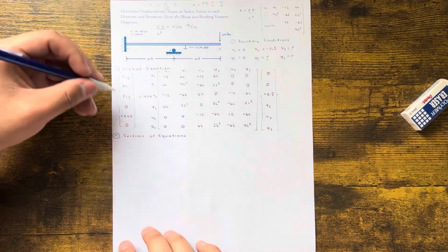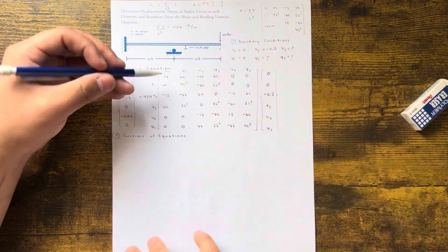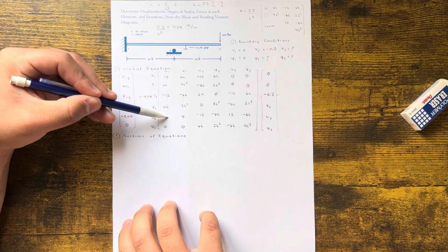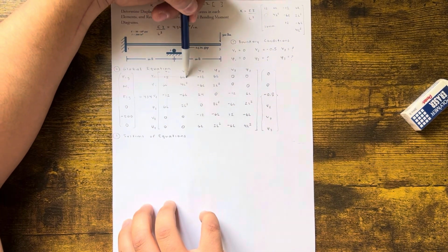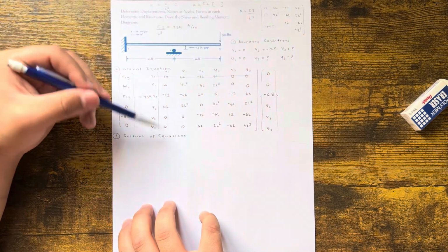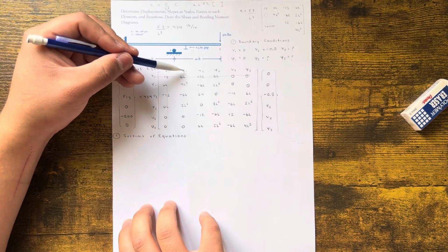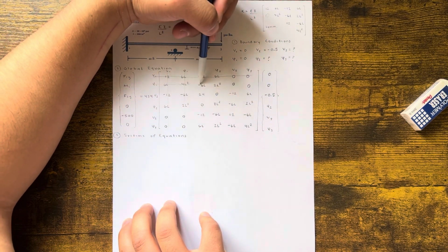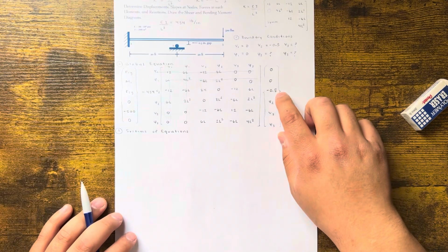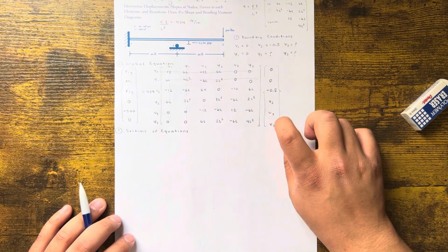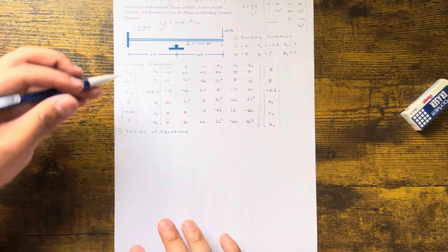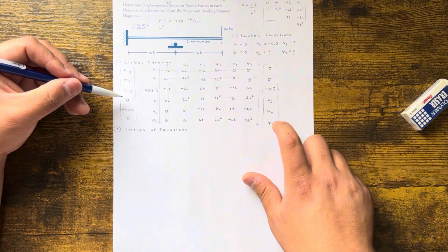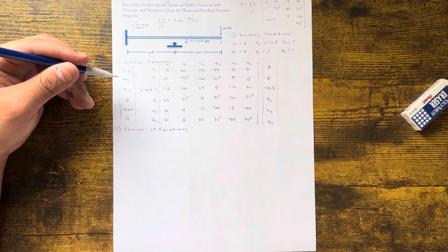So equations, right? When you have zeros, you can go ahead and cross out the rows for that column. So what we're going to do is this. V1 is 0. So you cross out that column, cross out that row. Same thing with Phi1, right? Phi1 is 0. So these go away. And that's about it, right? You can't cross that one out because that's a number. Phi2, V3, Phi3. It's a 4x4 matrix. In this case, we're going to solve for 4 unknowns, F2Y, Phi2, V3, Phi3. And then, yeah, that's pretty much it, right? It's just algebra at this point.